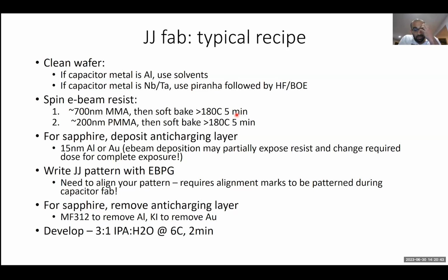Yeah, I would imagine that for e-beam resist in particular, you don't want it to come into contact with water or moisture, because that can ruin the exposure properties and development properties. So you want to make sure that the humidity it's exposed to is well controlled.